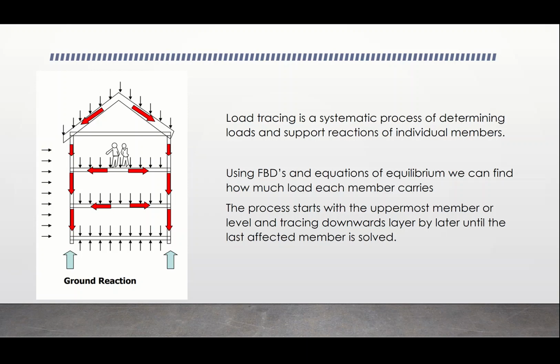Do we need to make this area loading into a distributed load? Then it goes to a concentrated load. We need to be able to identify what each one of those is doing and the loading that it's creating for the next member. So we do this by using free body diagrams and the equations of equilibrium, and we can find how much load each member is carrying.